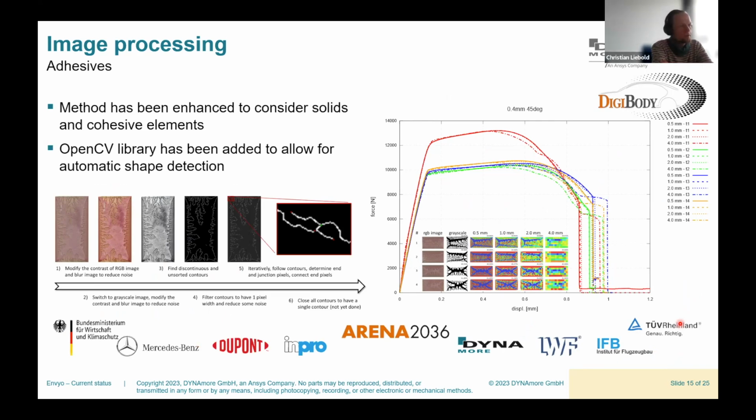So for the wood forming, we had the capability to do that with shells. Now we also map to solid and cohesive elements, so we can initialize a specific material model in LS-DYNA. We can initialize a damage factor, which is based on the effect of the viscous fingering.